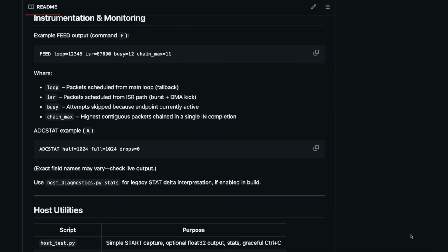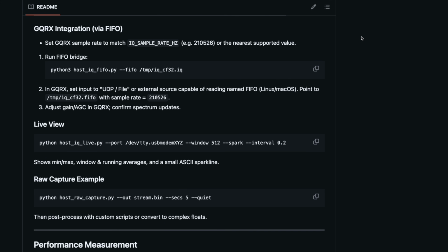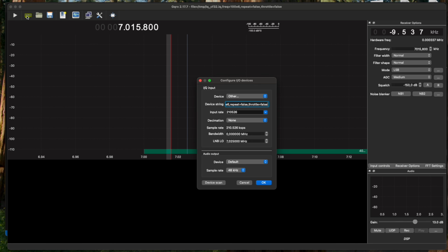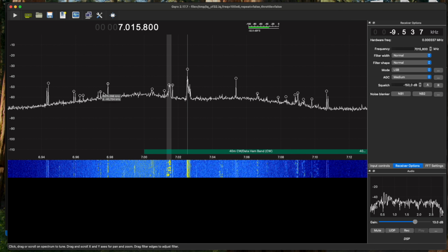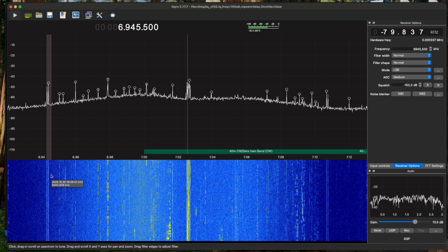Since I haven't gone as far as to make a complete integrated driver for GNURadio or GQRX, my Python driver simply dumps whatever the ADCs receive into a FIFO buffer via USB that GQRX can read at the sample rate the firmware is set to using the file source. That means we can't control the frequency in software, but have to tell GQRX what the local oscillator is set for when the buttons on the PhaseLoom are pressed to change the frequency to a different channel.